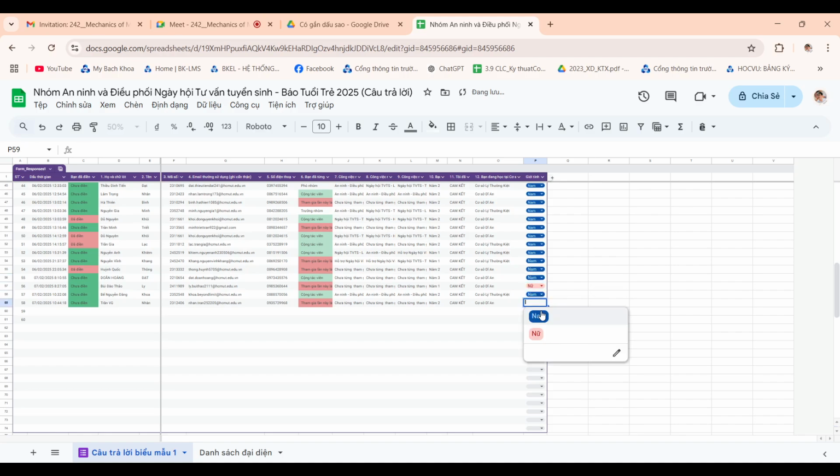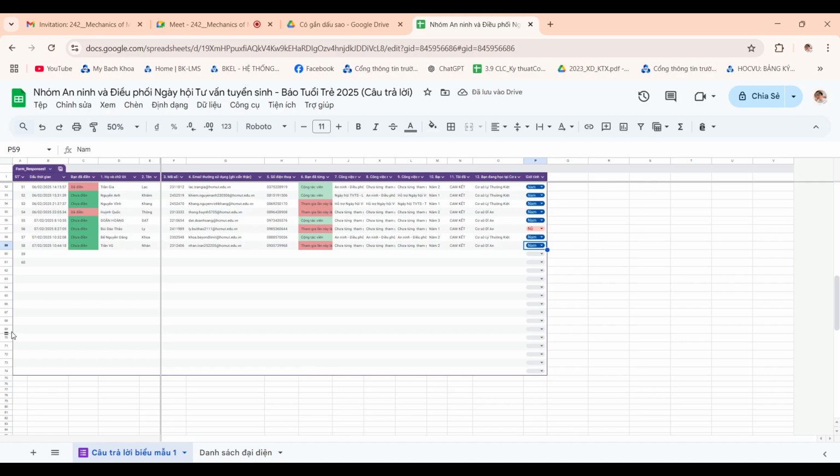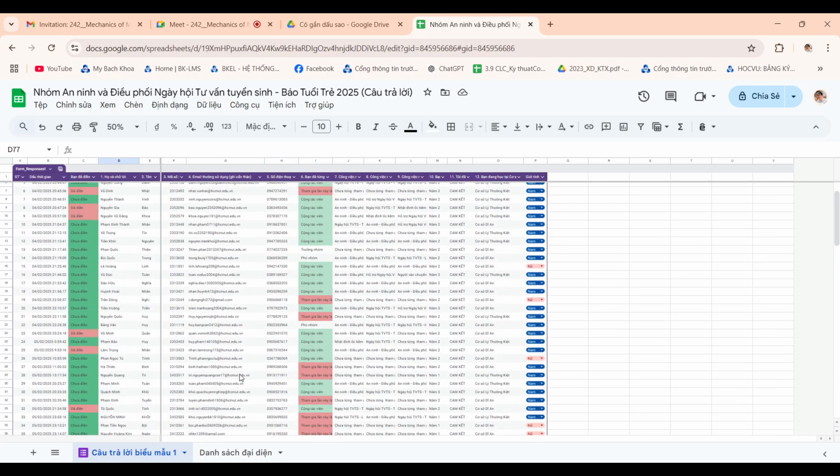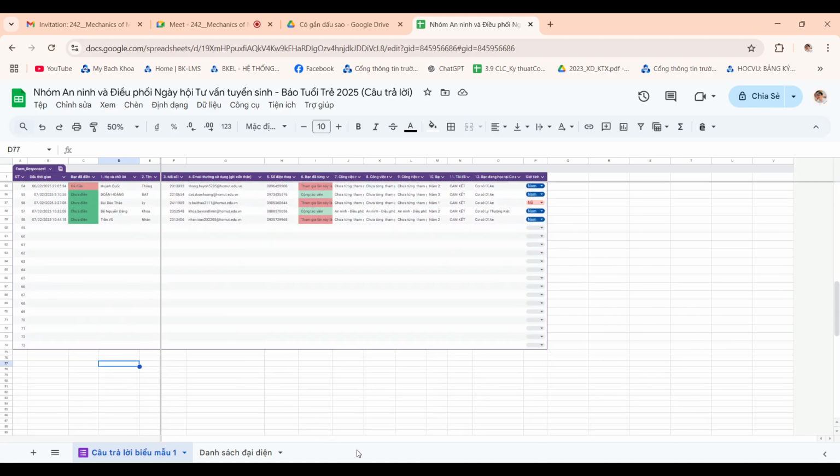So if you take upward as positive, you have 319 going up, minus 600 sine 45, minus 100, minus 200, don't forget the 200, plus BY, and you have BY coming out as positive 404. Sorry, 405. So that is really the solution of this little problem. So if you have made a mistake, please make a note of the mistake. Any questions, please?